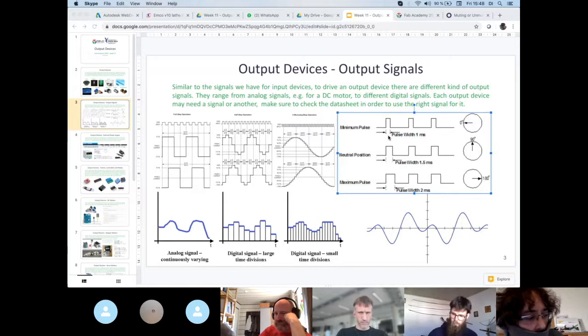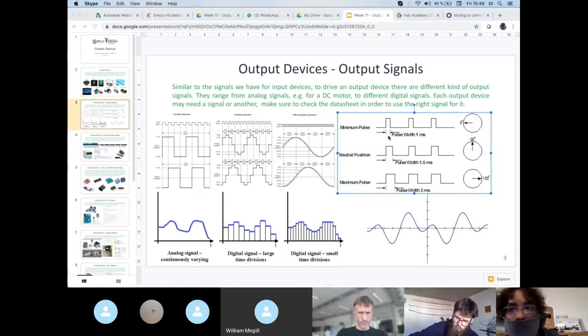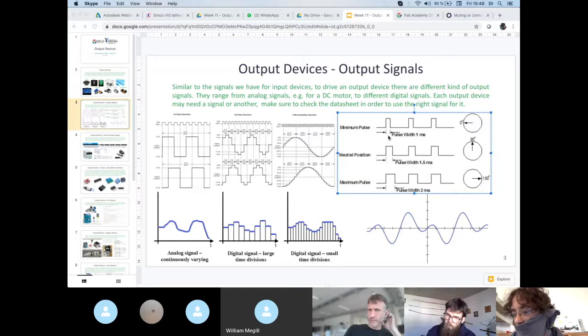In this case, guys, you can generate this by yourself with software if you want, but it's going to be, let's say, rather hard. You need to work with hardware timers and so on. So what you could do is just use a library. For example, for the Arduino, we have the analogWrite function, and it will generate the correct pulse for your motor.